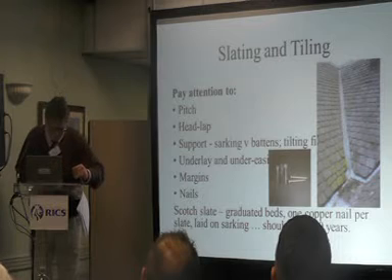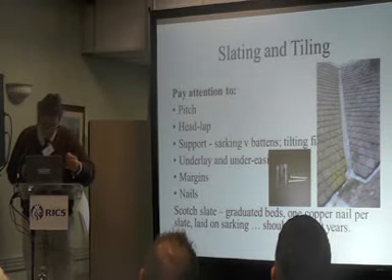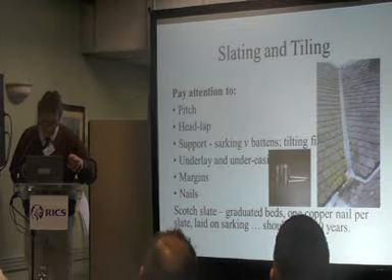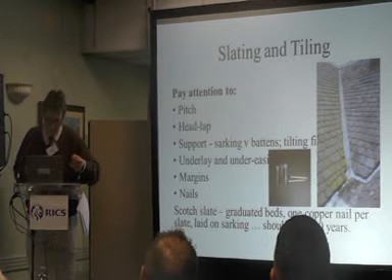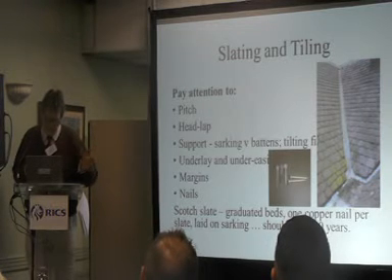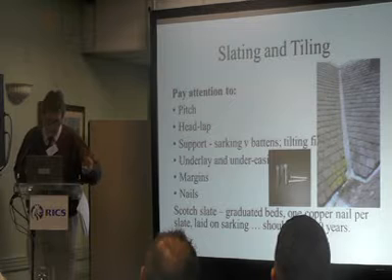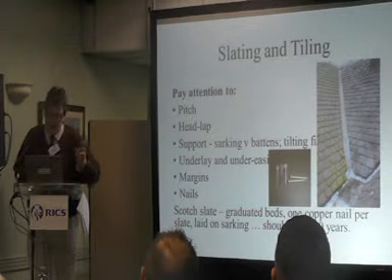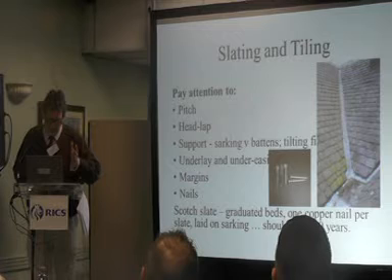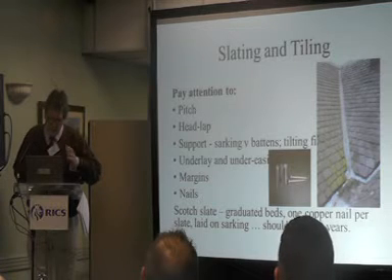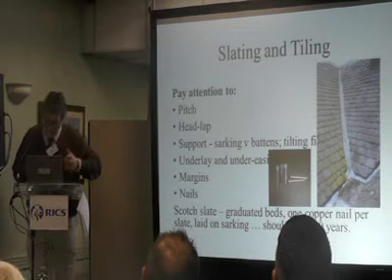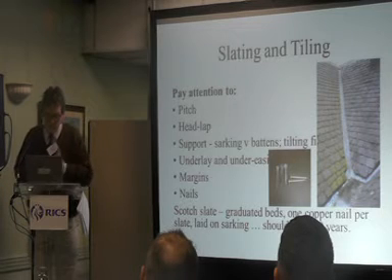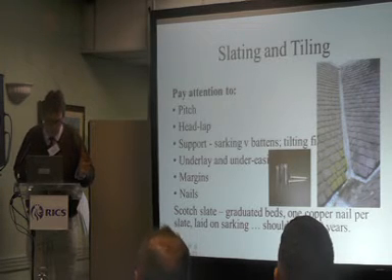Margins, I could spend a lot of time talking about slate and a half and the way to deal with abutments. The safest way with historic buildings, where you're abutting up to a little water table or parapet, is always the open water gate. It's the simplest, it's the one you can see if it gets damaged or blocked, and it is open for the water to come down. And the roof is sitting on timber, so it's going to move much more than stone at the margin.